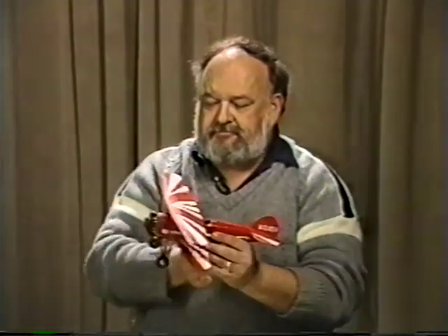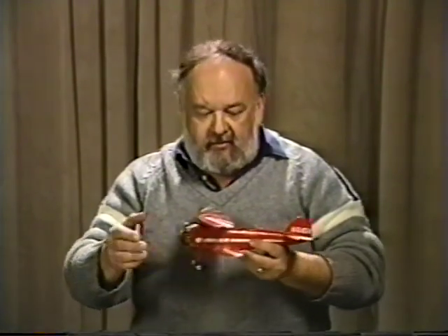The trickier one is the one in pitch, where you have CG travel that you have to worry about. You have several other things. Your wing itself generally is an unstable wing. You have a little camber to it, or when you put your flaps down, it very definitely is unstable. So you use a tail to give you your stability. Look in the books, look at the numbers, and take a good idea from there.